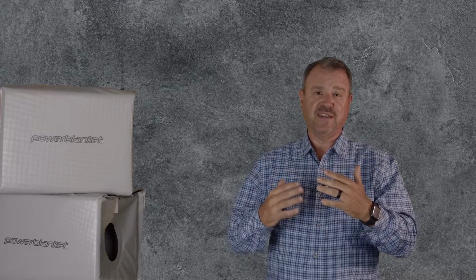How do you tell if your heater needs to be replaced? A couple of things that are really obvious is, number one, if the performance reduces when power is applied, you know that you've lost heating elements or the ability to create heat. Heating elements, like any mechanical device, lose about 5% of their performance every 5 years. Sometimes when other things come into play, they'll go faster or slower.